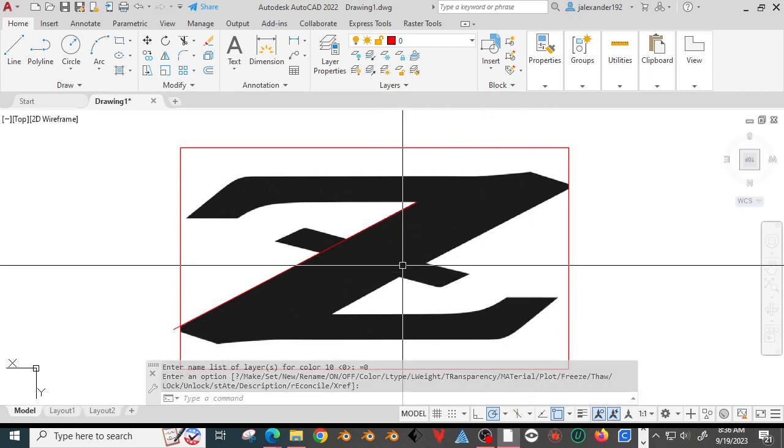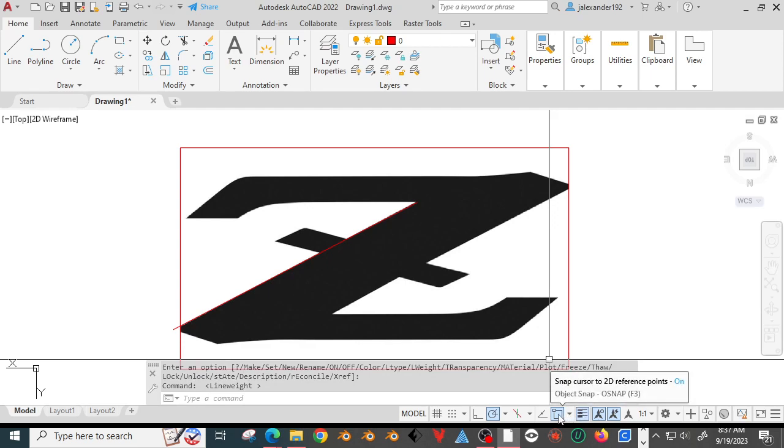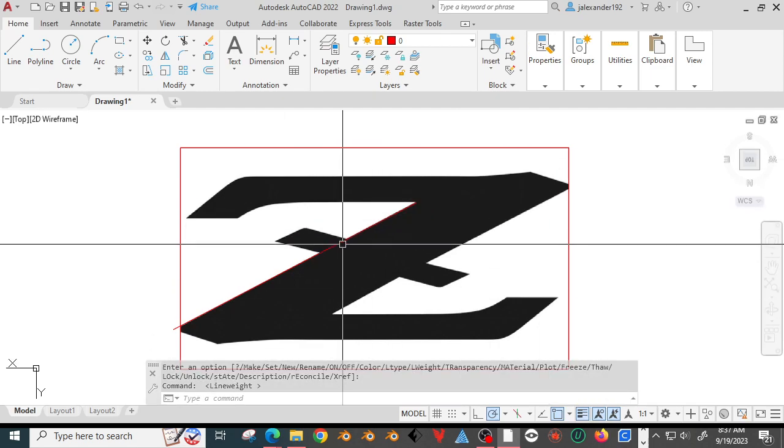The other way is to make your line thicker. So in order to do that, we have to turn on what's called line weights, which is down at the bottom. These are basically toggle buttons. I'll make this one blue. It's right next to the square and next to the Mitsubishi symbol. So that's on because it's blue and nothing really changed.